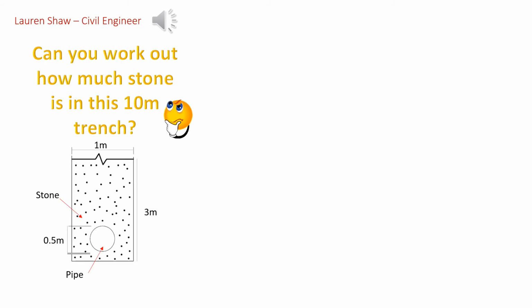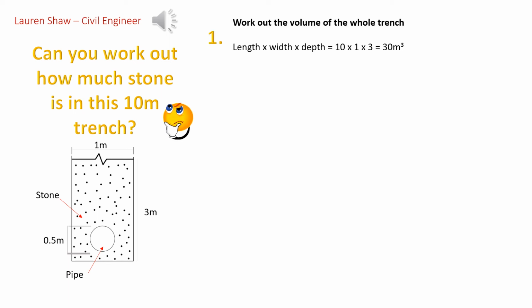My name is Lauren and I'm a civil engineer on a construction site. At work, I use pi when I need to calculate the volume of stone in a trench that has a pipe in it. Have a look at this trench. How much stone do you think is in this if it's 10 meters long? Let's work it out. First, work out the volume of the whole trench by multiplying the length, which is 10 meters, by the width, which is 1 meter, by the depth, which is 3 meters. This equals 30 meters cubed.